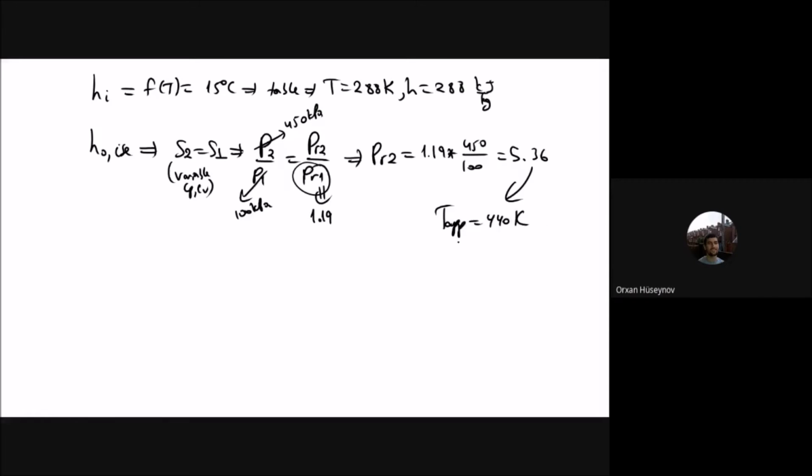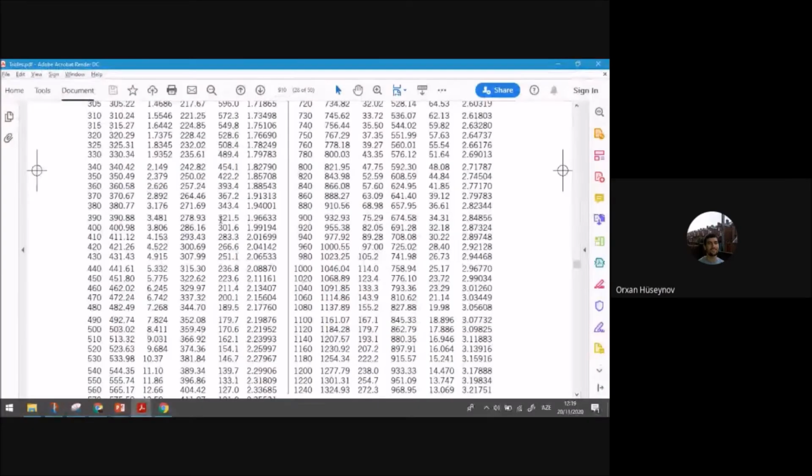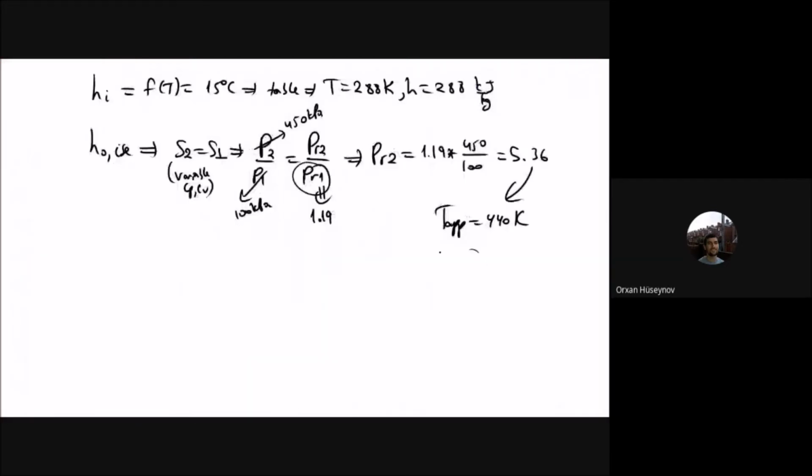Okay. And then if I know the approximate temperature here, from that approximate temperature, I can find the enthalpy value, which is the second one. So from here, enthalpy approximately will be equal to 441.61, which makes 442 kilojoules per kilogram. Okay, so by using isentropic relations, I will summarize what I have done.